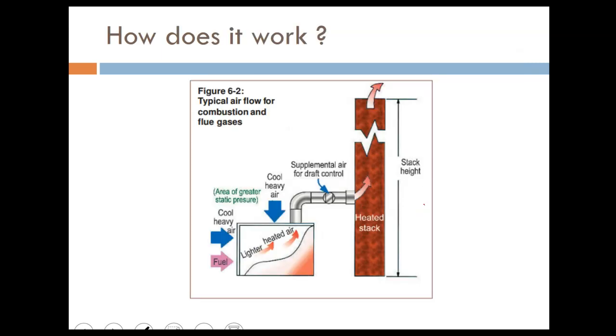We did discuss that. How does it work? It's just more illustration of how the stack works in pulling air into it. When everything fails and the stack is too long or too wide, we can't achieve proper draft. And again, how do we know if there's a proper draft or not? We're gonna do a draft measurement in the chamber, over the fire, and on the stack to see what the draft is. Are we pulling air or not? Because otherwise we'll have some backdraft, and that means we will have CO2, possibly carbon monoxide inside the house.